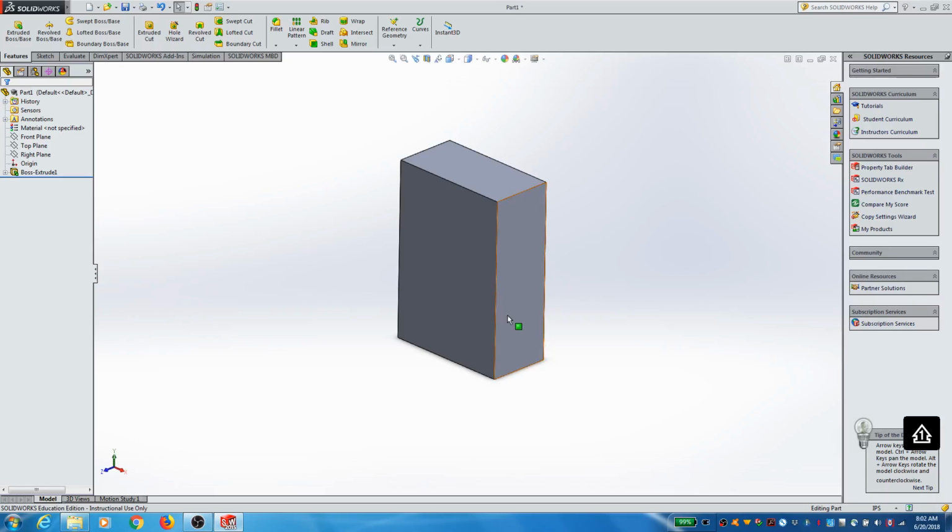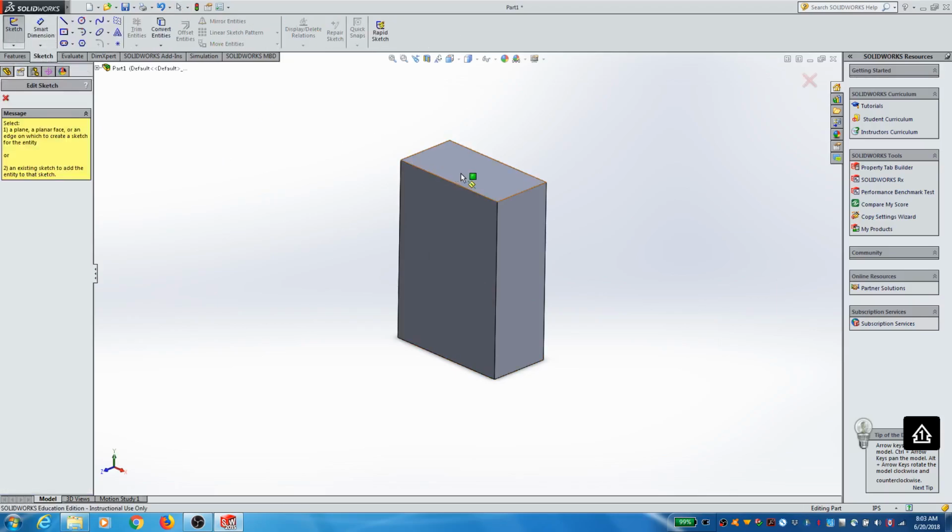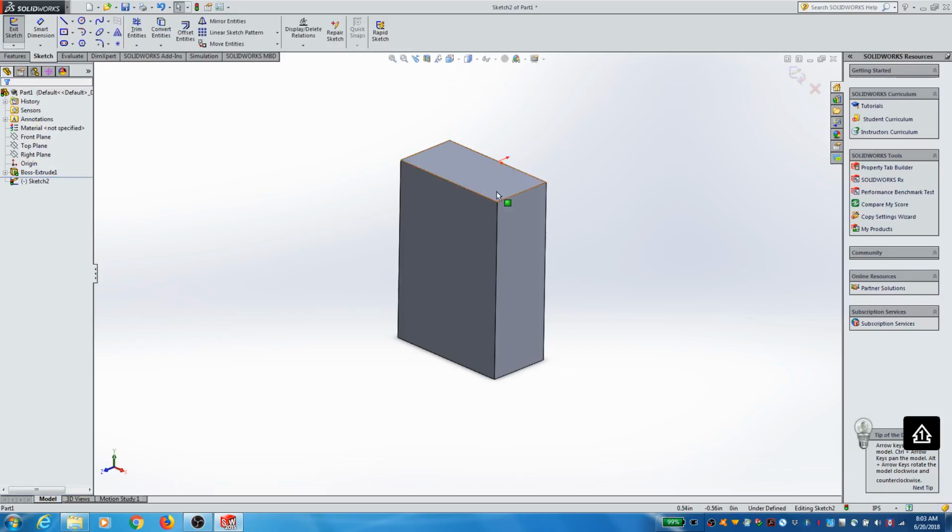All right, so I want to go back to what we were doing. So we made this first block, all right? And we did that by drawing a rectangle and then doing an additive extrusion operation forward. If you remember, Gianna's puzzle block had a little window cut out here, right? So it's kind of L-shaped. So I'm now going to make that, okay? So I'm going to go back to sketching, and I am going to sketch on this top surface. Notice it says selected surface to sketch on. I'm going to select this top surface.